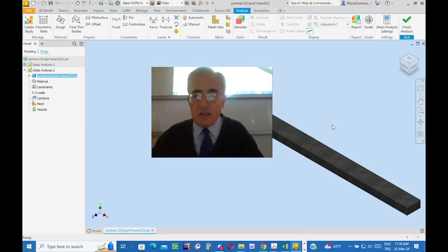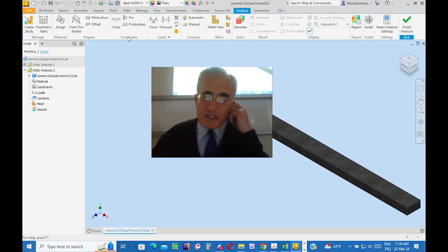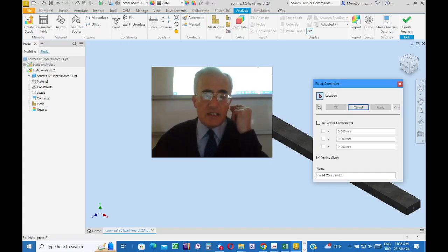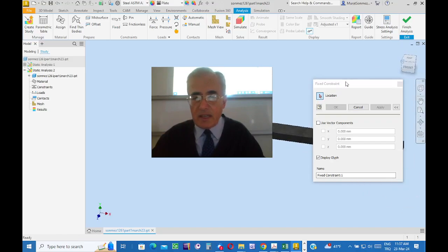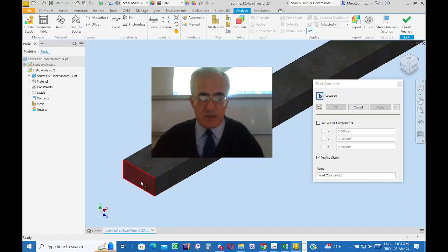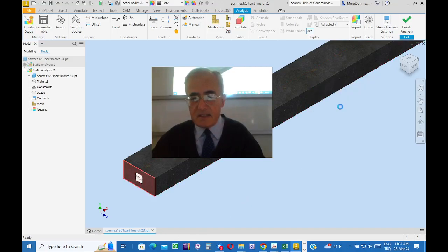Okay. And then yes, the next part is the constraint panel. Click on which kind of constraint you have. In our example, it is a fixed connection. Well, this surface has been welded, fixedly connected. And then say okay.